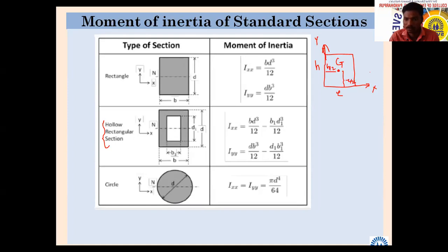For a rectangle, it is very simple. So this is the centroidal axis, GG. Once we want to find the moment about the centroidal axis, that formula is here. So students remain mugging up. Mugging means memorizing. Ix is equal to b d cube upon 12, because this vertical dimension is d, horizontal is b. We should not mug up this.